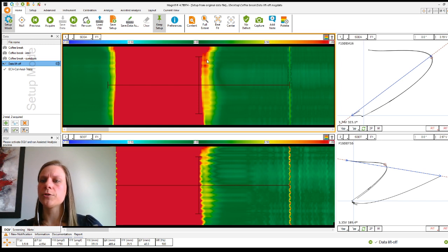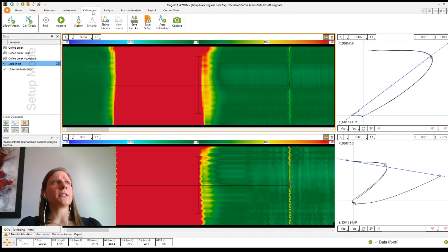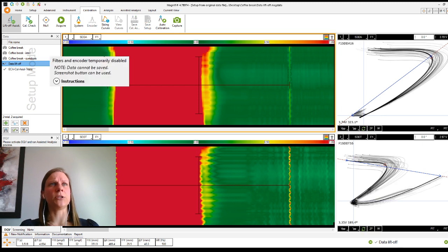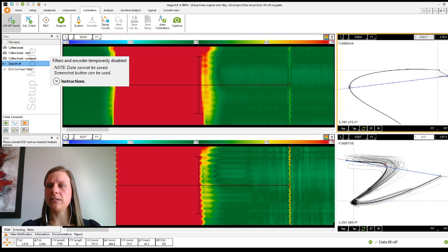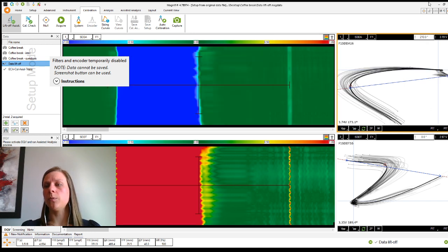So the cursors, once again, I was reading back data, so the software did not automatically place the cursor, but this is the actual display of the cursor you would be getting when using the tool. So if I go back in the tool, I have the render cursor display in the impedance plan. I see that the liftoff signal is not on the horizontal, so you need to use the rotation button at the top of the impedance plan, and then you can rotate the signal to the position you want.